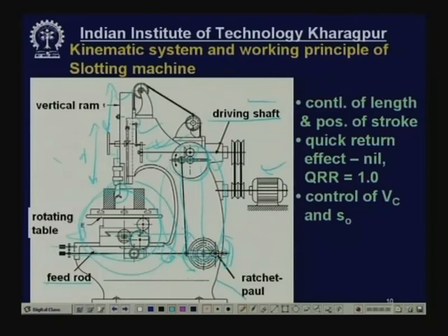Now, when this wheel is engaged with this wheel, which is nothing but a gear fitted into the screw, that gives this table, the upper slide, x motion, feed motion, and when this is engaged with this gear, this is connected to the worm, that is connected to the worm wheel inside, that makes this job rotate, all right.